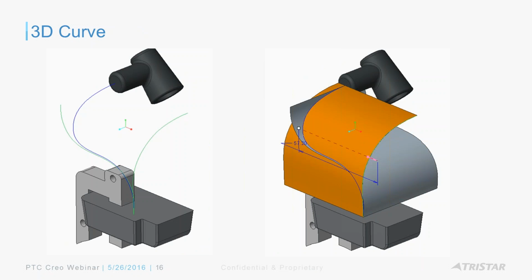One quick example here on speaking about curves. How do you create a 3D curve? Yes, you can import CMM point cloud data into Creo Parametric and generate a curve through those points. However, there are times where you might know the resulting curve in two perpendicular planes, like two 2D curves, which can be captured as sketched curves, and then you can simply intersect them without the need to even create a surface for the intersection.